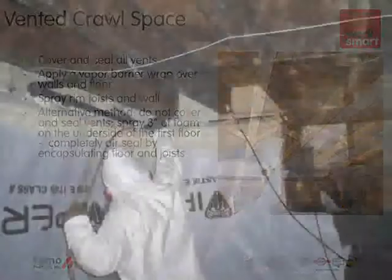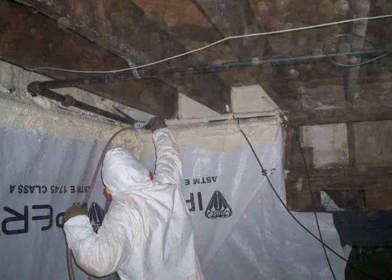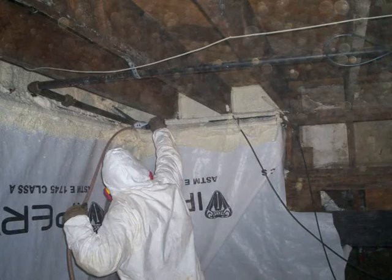This is a picture right here where you can see the white vapor barrier wrap that they've brought up to the rim joist, and in this case they're insulating the rim joist, and then they're starting to insulate down the side of that vapor barrier wrap. They will eventually insulate all the way down the vapor barrier wrap until the vapor barrier turns into the floor.